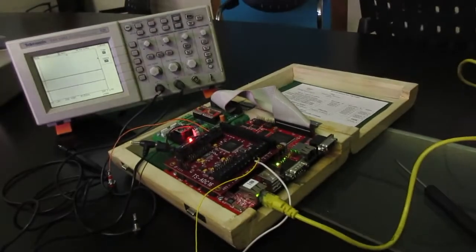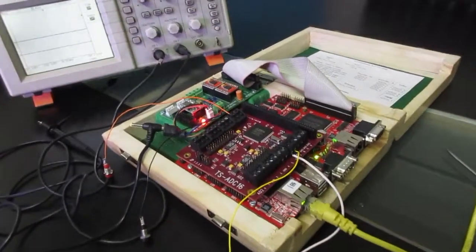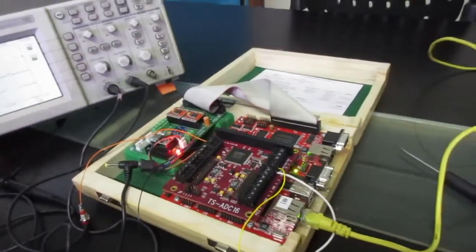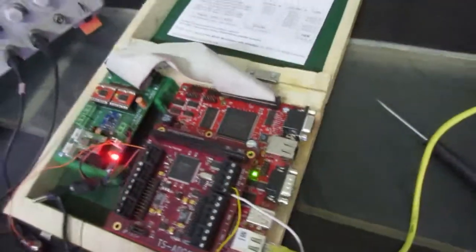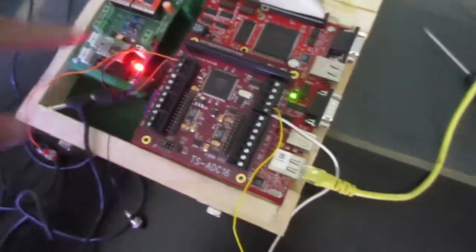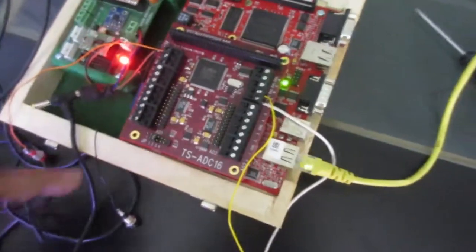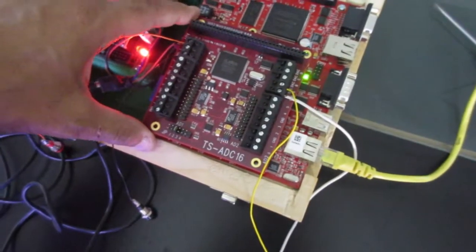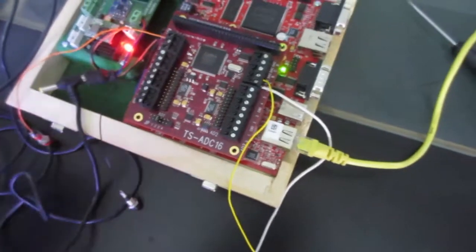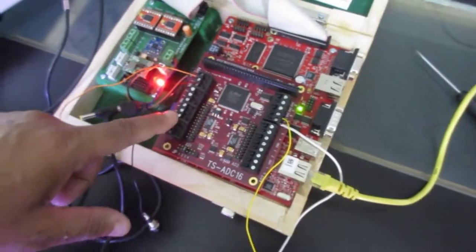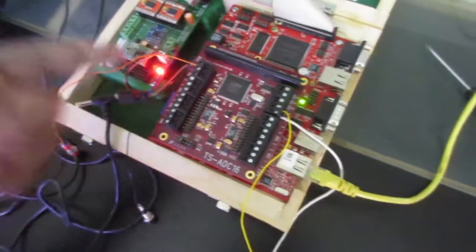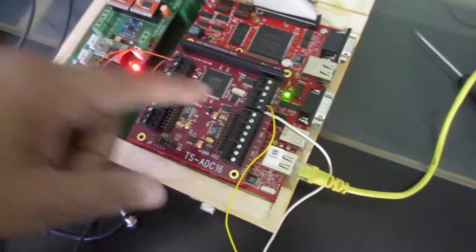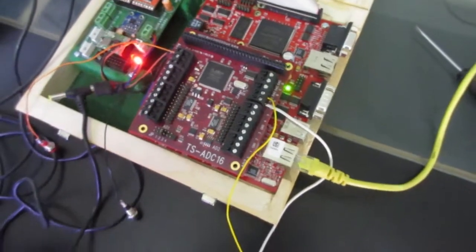It also has the capability to extend its control or any algorithmic models into the hardware. It can convert them into C code and that can be downloaded into boards like this. So today I would be using a TS7300 board, that is the bottom one, and on top of it, it has been plugged with an analog to digital converter card. It has 16 analog input channels and 4 analog output channels. The inputs are 16-bit resolution and the output DACs are 12-bit resolution.